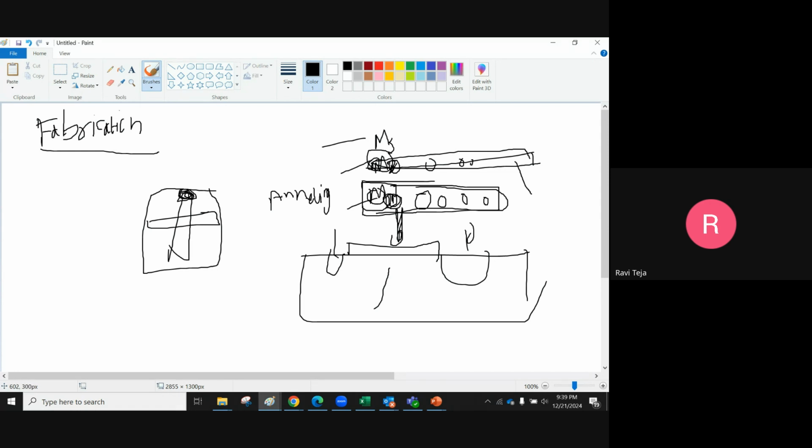Now, if I have an antenna violation on M3, as I told you, we will use metal jumpers. The technique to avoid antenna violation is metal jumpers. If there is any charge on this metal, metal jumpers in the sense we need to chop some metal here and then go for a higher metal.